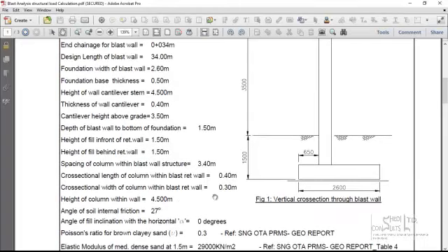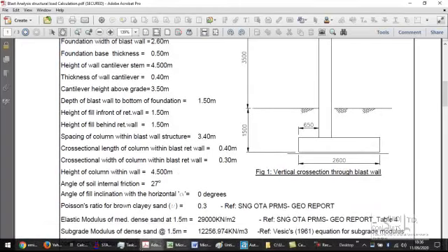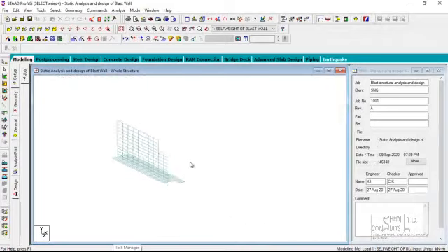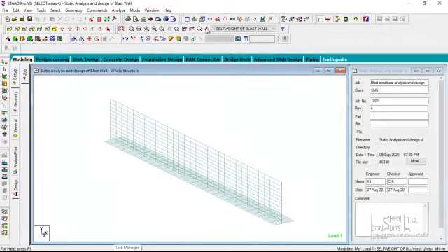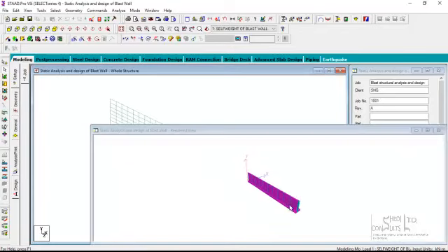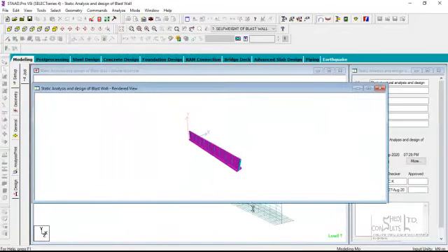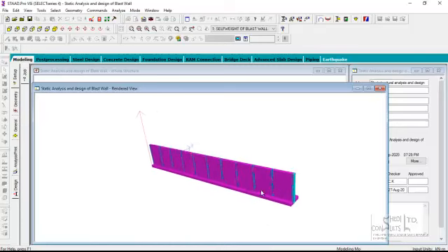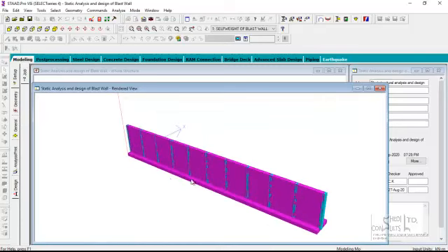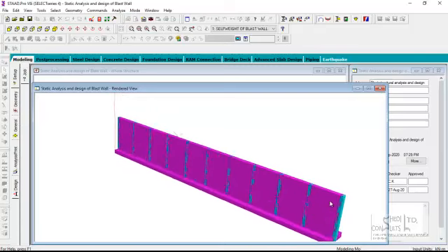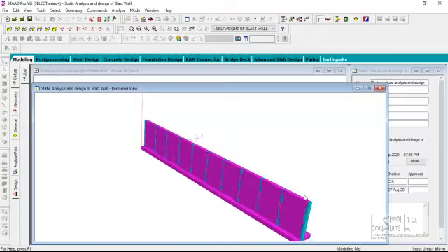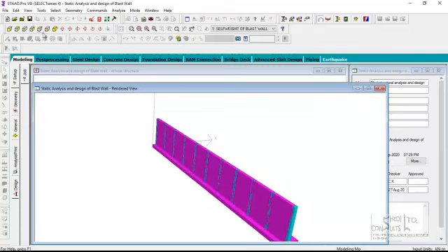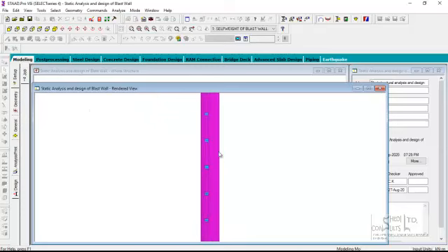Now this wall is designed to have columns in between. Because of the wall's length and the corresponding blast loading that was calculated for the shock front and its side, to prevent catastrophic failure of the wall, it is designed to have columns in between.